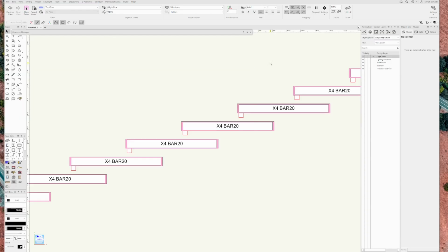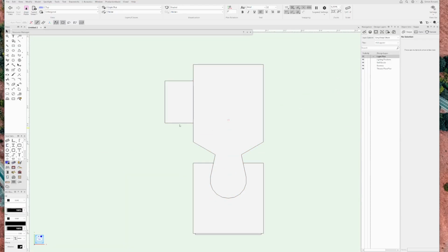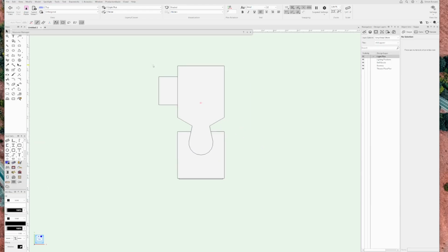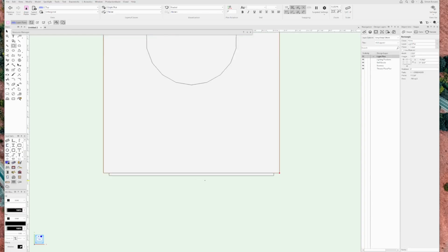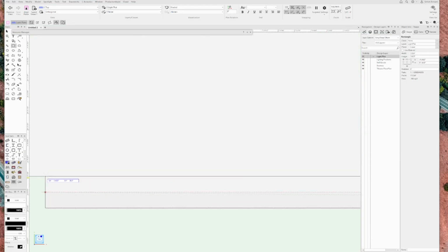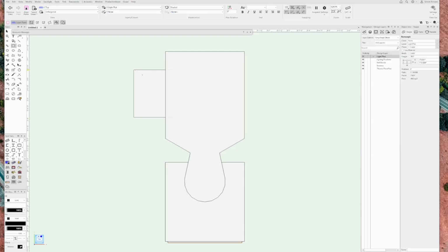To make sure I have the proper geometry to import in my symbol, I'm simply going to flip to the top, and then over the outline here, I'm just going to draw a few rectangles on top. Just 2D rectangles. One here. There's one I missed. There's one here. There's a really tiny one below. There's this one that represents the connectors.